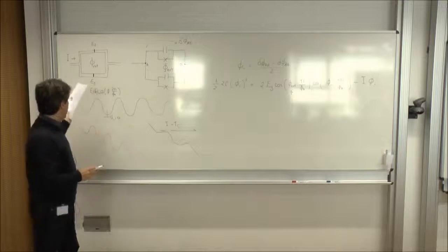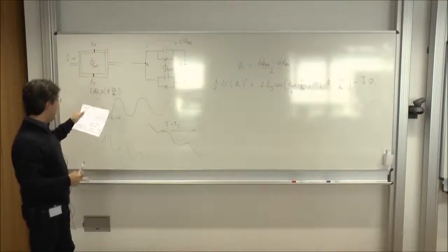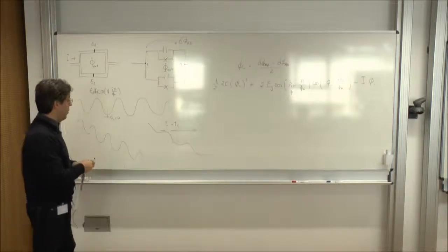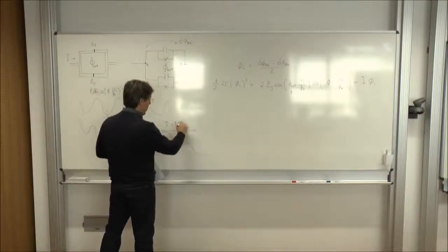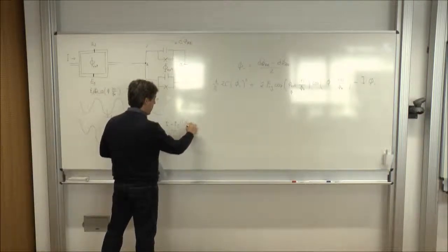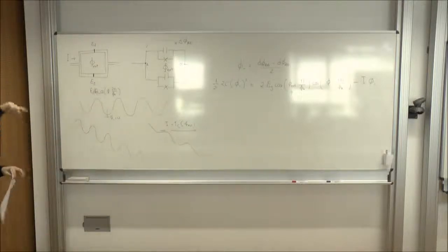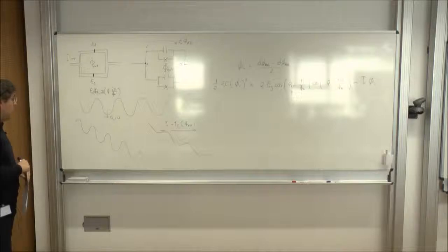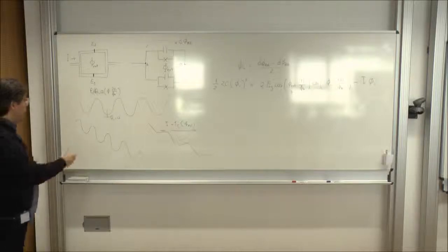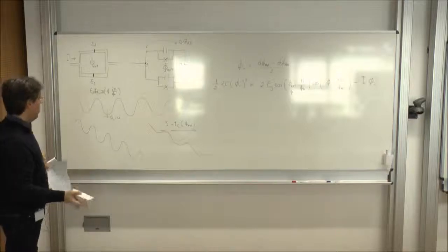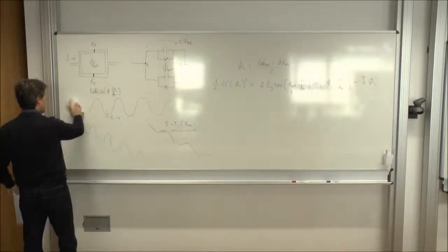And you will see that the first experiments that we will show with flux qubits, they use this device for measurement, because this current depends on the external flux. So your switching happens depending on the flux which is inside this loop. So you can use this to measure the tiny currents that form part of flux qubits, for instance.